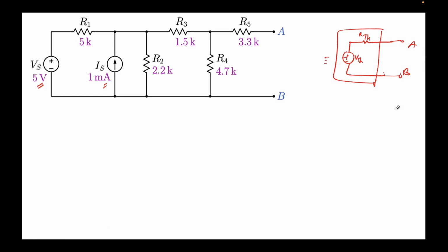Yeah. So I told you this is an equivalent circuit of this. However, there is another equivalent circuit, and it looks something like this. This is the voltage equivalent, and this is the current equivalent. Again, this is the black box. We don't care what's inside. We only care what's coming out from A and B. This one is usually referred to as a Thevenin circuit, Thevenin equivalent, V Thevenin, R Thevenin, and the corresponding ones are a Norton. So this becomes IN, and this becomes RN.